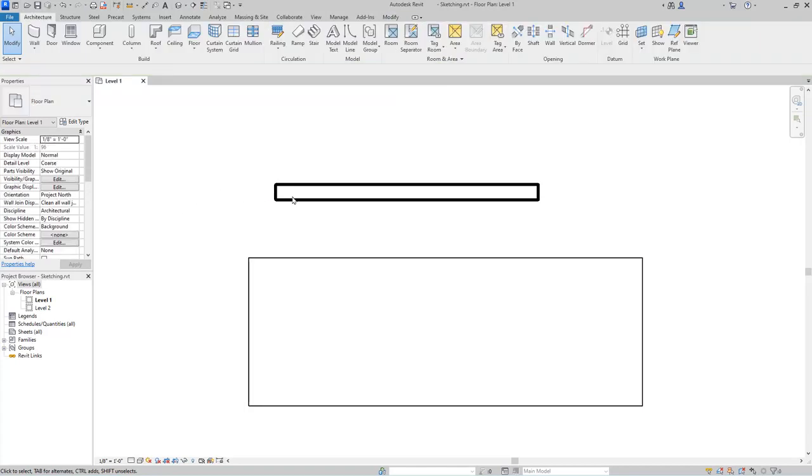As you have seen, when creating sketch-based elements such as floors, Revit goes into sketch mode, and you must create a closed sketch to define the perimeter of the element. But when creating line-based elements such as walls, you simply indicate the path for the elements.